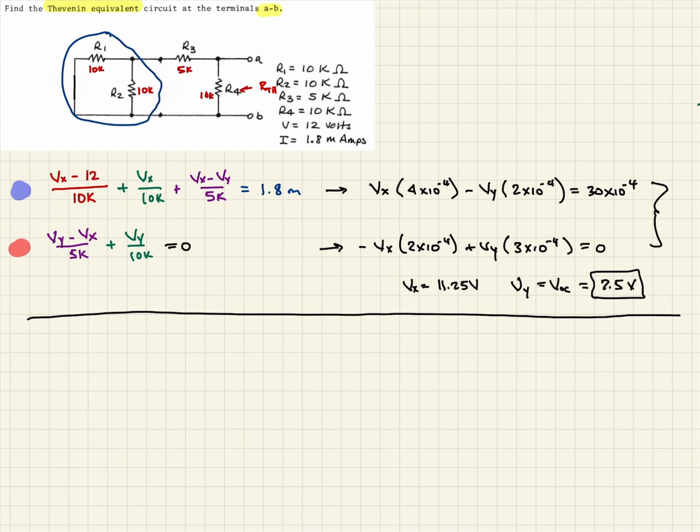And so anytime you have two of the same value in parallel, you can replace it with one resistor of half the value. So we can do that pretty quickly. So let's do that. So then all of this is gone. Sorry about that. And this is still gone. And so this will now be 5K. Remember, two 10Ks in parallel will give us a 5K in its place.